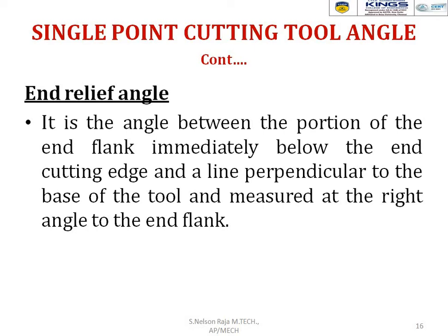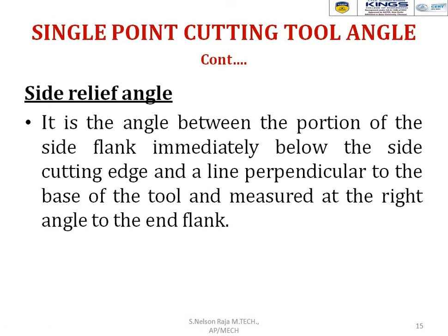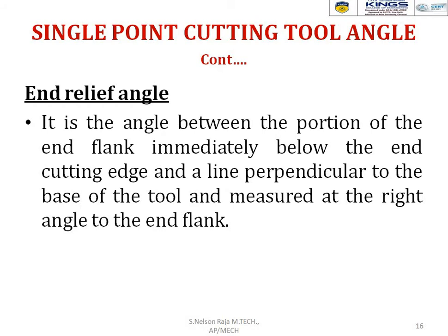And the end relief angle. It is the angle between the portion of the flank immediately below the end cutting edge and the line perpendicular to the base of the tool, measured at right angle to the end flank. Side relief angle and end relief angle are quite similar. So what is the major difference? A right angle to the end flank for the end relief angle, and a right angle to the side flank for the side relief angle. That is the only difference between the side relief angle and the end relief angle.